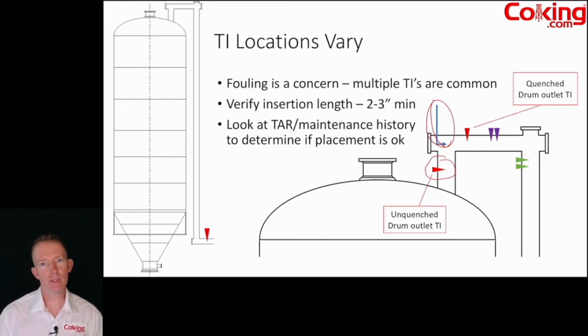Now, there are some sites, especially newer ones, where they pay attention to this value for optimization purposes, and they've gone with 2 thermal wells. So this is the purple example that we have there on the diagram. The purple ones, anytime you see 2 of the same indication, it means it's very important and/or unreliable. The purple is still in that horizontal piece of pipe before you turn coming off the cutting deck.